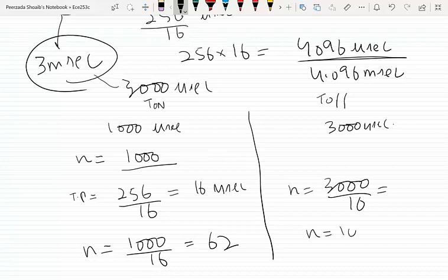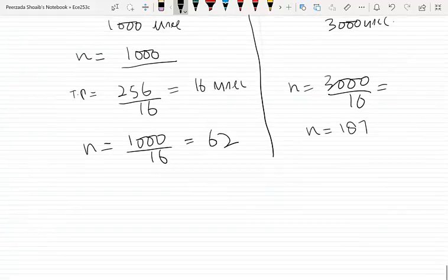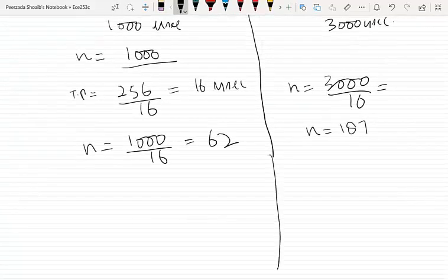So in this case, the value that needs to be loaded into the timer counter register is equal to 255 minus 62, that is equal to 193.